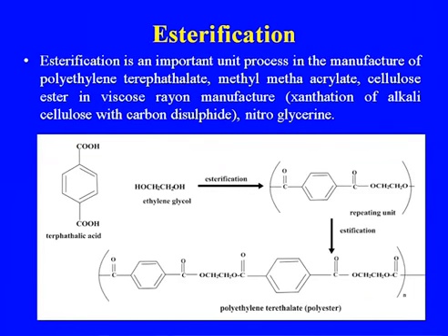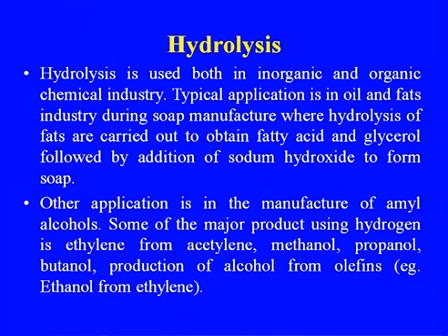Esterification is an important process in the manufacture of polyethylene terephthalate, methyl methacrylate, cellulose ester in viscose yarn manufacture, nitroglycerin. Hydrolysis is used both in inorganic and organic chemical industry. Typical application is in oil and fat industry during soap manufacture. Hydrolysis of fats is carried out to obtain the fatty acid and glycerol, followed by addition of sodium hydroxide to form soap. This is the process we are using in the case of the soap manufacture.